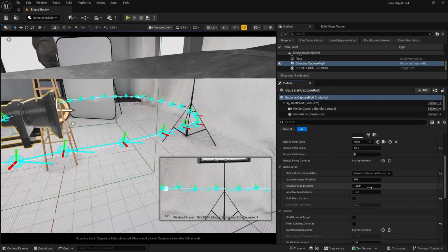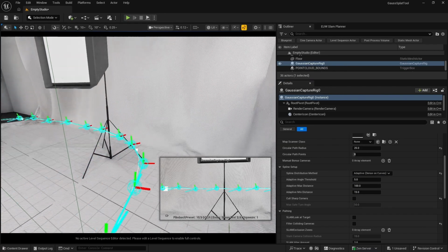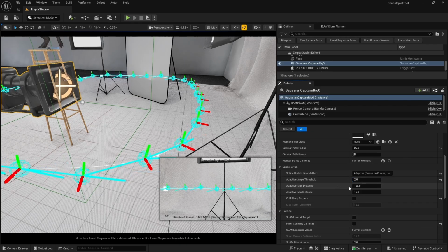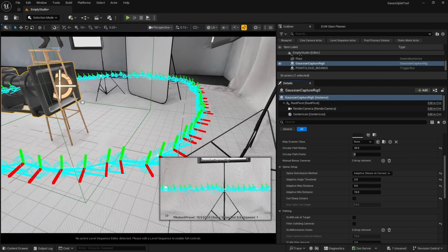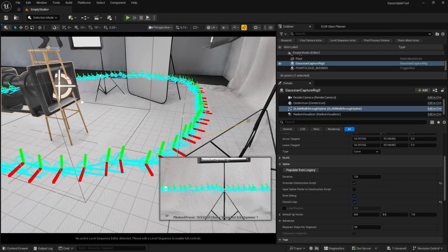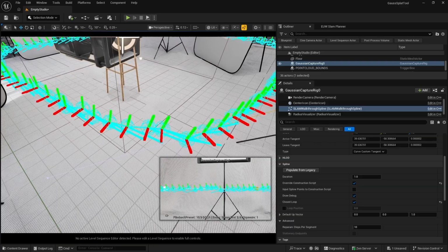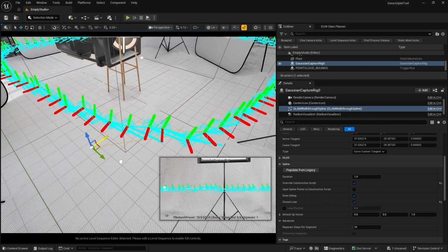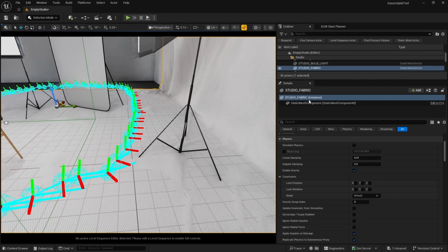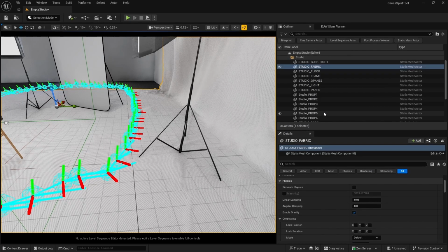And the other method is adaptive dense spaced curves. This is for instance where you want to have more points in regions of high curvature along the curve. So you use things like these with a threshold of 2, maybe 5. So you have more point distribution where the curve really bends. Let me see, for instance, here. I'm just trying to make this point sharp, so you see the point distribution there.